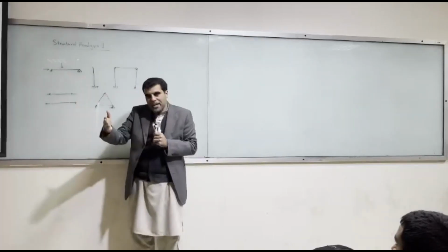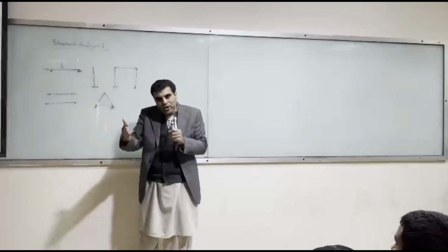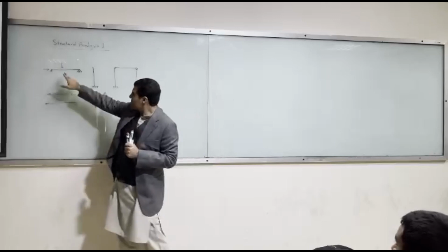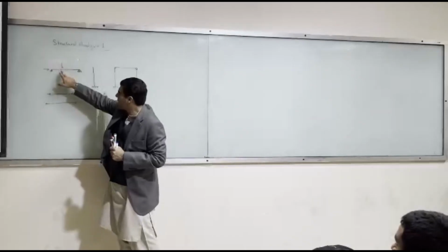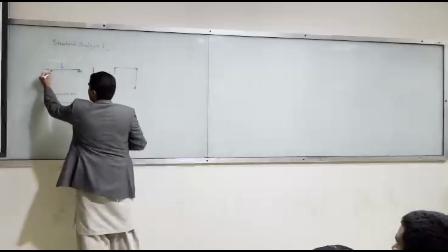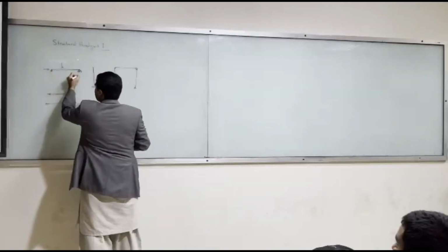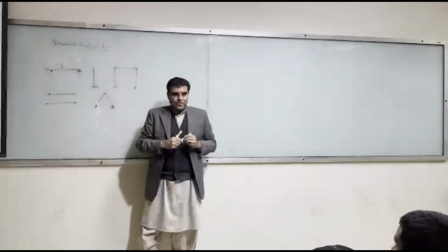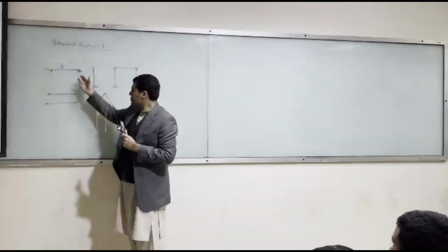And through these bending moments and shear force, the load is transferred to the support. Do you understand my point? You apply the load over here. How do you get the reactions? Through shear force and bending moments. You get the reactions over here.